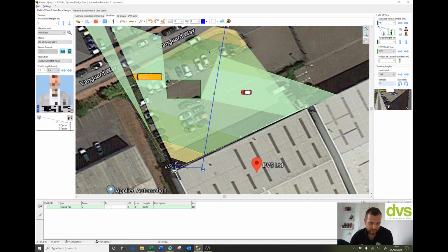Under here you've got your cable routes, and you can actually fill that in, description, you know, Cat5e link cable. And again, you don't have to, sorry guys, I spelled it wrong. You don't have to show them. I can turn that off and then it shows or doesn't show the cable route, but on the report, it will have that. So again, a really handy piece of information, and it even gives you the length, 60 meters. So you know, to go from there to there to there is going to take you 60 meters of cable. So a really, really powerful piece of software.